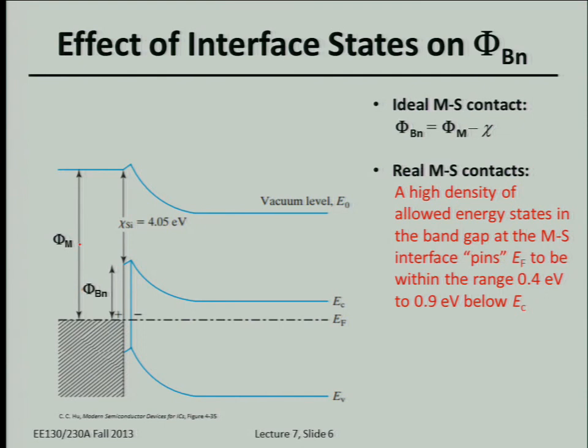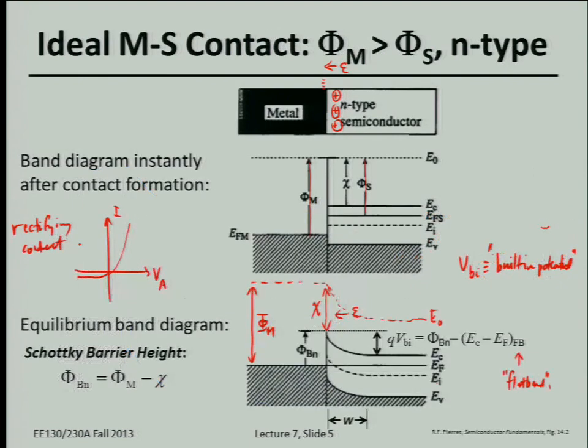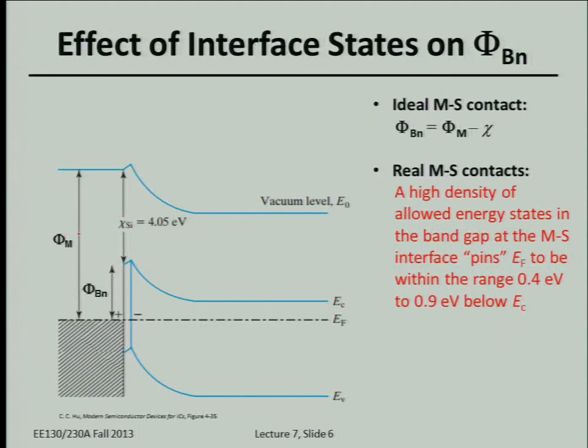Is this similar? Okay, so the band bending in the semiconductor is similar to the depletion region in a PN junction. You're absolutely right. The reason we have that energy band bending is because the surface region close to the metal is depleted of electrons. Electrons, upon contact, really prefer to be in the metal. So the surface region is depleted of electrons, and we'll come back to that. And so you have charge there due to the.